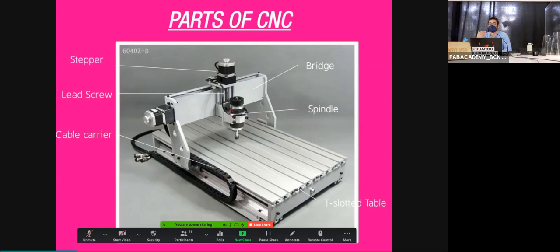So, if you want to cut 200 millimeters or 20 centimeters of material, you need to find a machine that has a bridge higher than 20 centimeters. Usually, it's one third more of the size. That depends a lot on the mechanics of the machine.